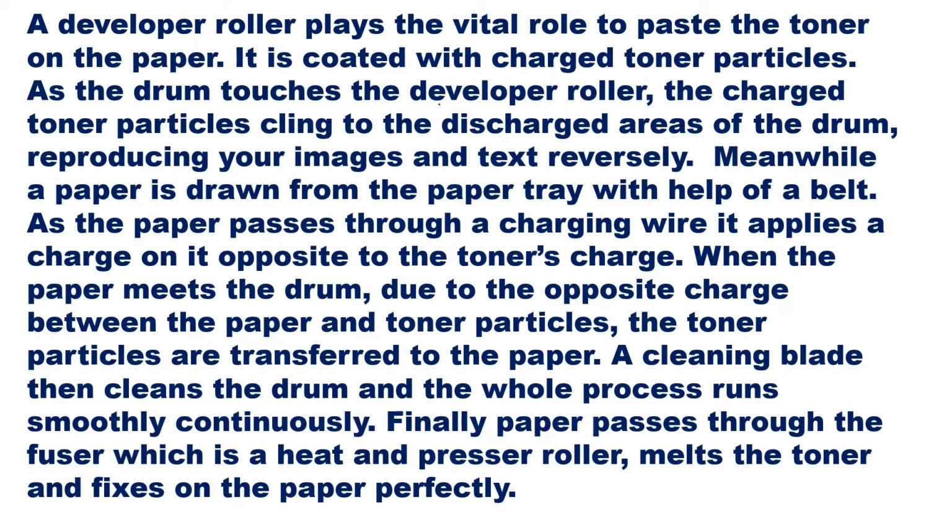Then you can see a developer roller plays the vital role to paste the toner on the paper. It is coated with the charged toner particles. As the drum touches the developer roller, the charged toner particles cling to the discharged areas of the drum, reproducing your images and text reversely.